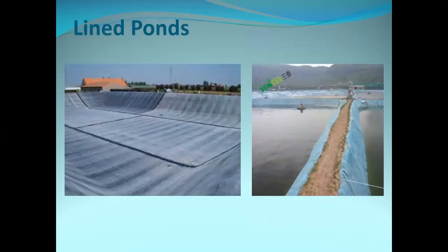Another thing you could do with ponds: let's say for instance things are real rough, and you really can't find good soil, or you really want to do pond-based aquaculture on some available land that you have, but the land is not 100% clay, and it's not very suitable to dig ponds or set up a levee type pond, right? Another thing you could do, you could actually line the pond. So you're digging out your pond as usual, but you're not dependent on clay to compact the bottom anymore. What you could do, you could take liner.